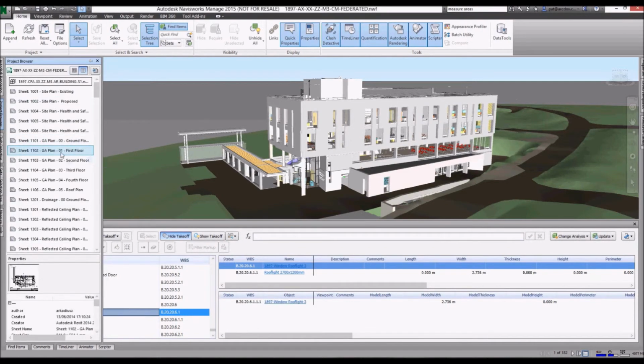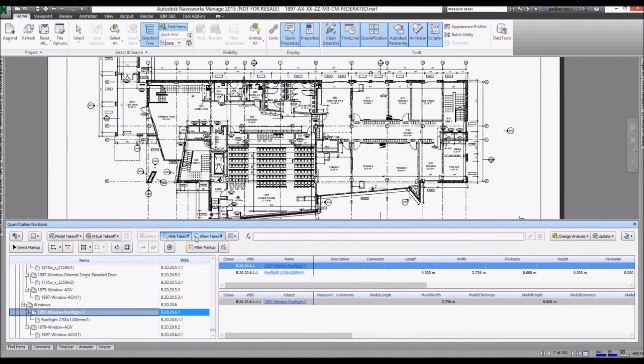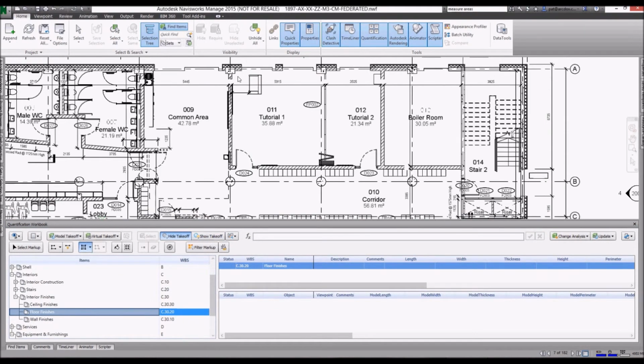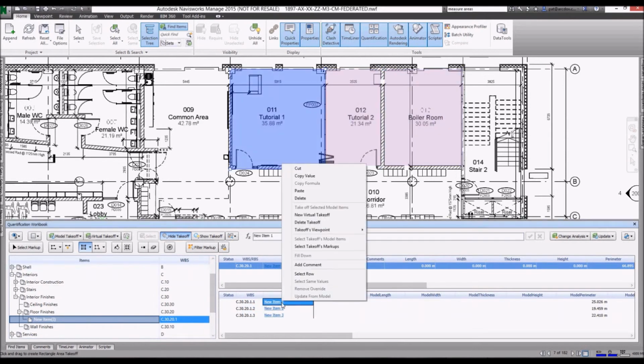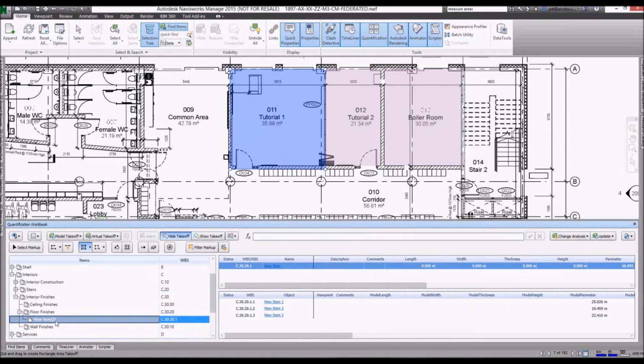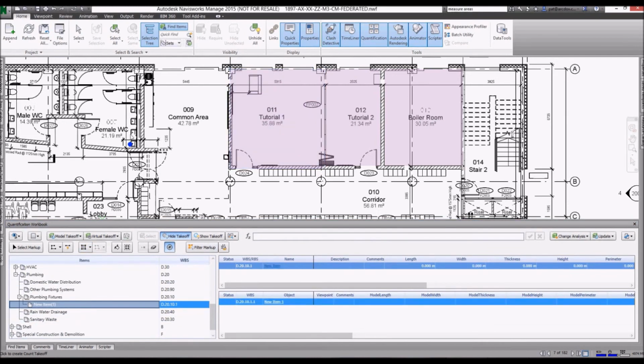As in 3D, in any 2D sheet view, it is possible to isolate or highlight items already measured. Tools such as the Area Takeoff tool will allow takeoff of finishes where these have not been specifically modelled, and these areas will be added to the workbook. Also, individual items can be taken off by tagging these in the sheet view.